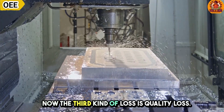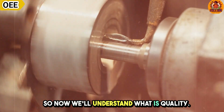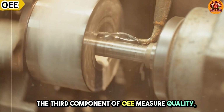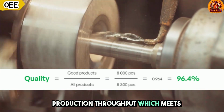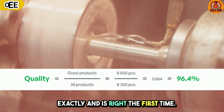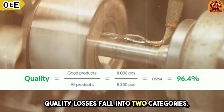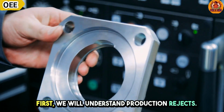Now the third kind of loss is quality loss. So now we'll understand what quality is. The third component of OEE measures quality, which is simply the proportion of actual production throughput which meets the customer specification exactly and is right the first time. Quality losses fall into two categories: production rejects and startup rejects. First, we will understand production rejects.